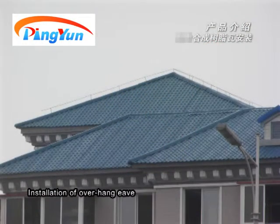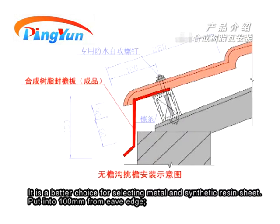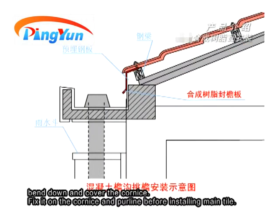Installation of overhang eave. To enable effective roof drainage and protect the wall under the eaves, overhang eaves should be installed. Metal and synthetic resin sheet are a better choice. Put it in 100 mm from the eave edge, bend down and cover the cornice. Fix it on the cornice and purlin before installing main tile.